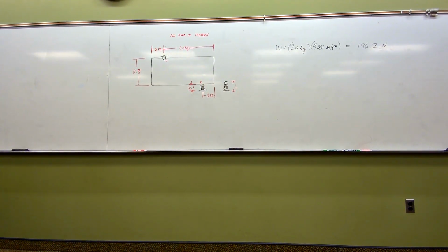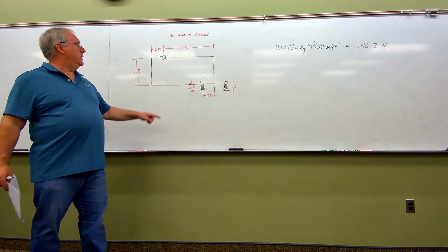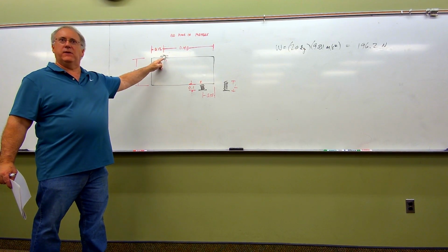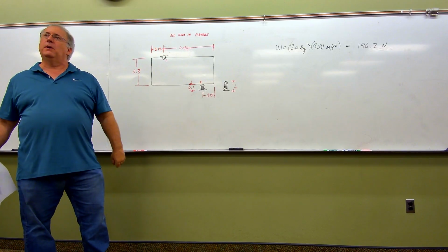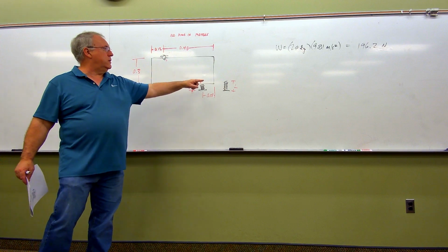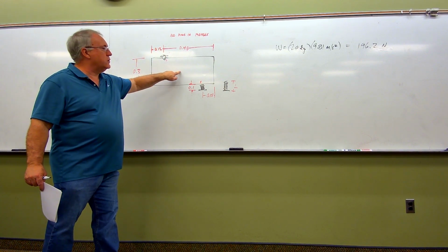So, okay, now the 196.2 newton uniform rectangular plate is supported by an ideal pivot at O. Man, there's a lot buried in this one. We just saw the word uniform, telling us that this plate, even though you could argue it's not exactly uniform because there's a pinhole in it, they're telling us it is, so just treat it that way. So since this plate is uniform, that 196.2 newtons of weight is going to be applied right through the geometric center.